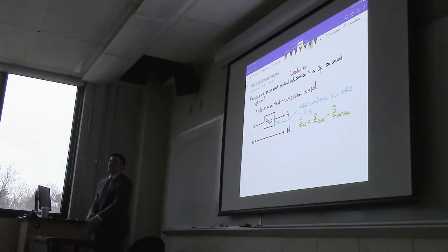It just has to do with the sign convention that we're using. It could also be represented as a plus. But the main point is that the total impedance along this chunk of the line is equal to a self-impedance, as well as a mutual impedance with the other two phases, which are not shown in this picture.